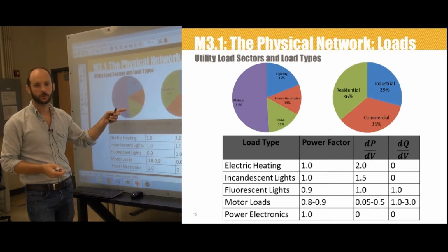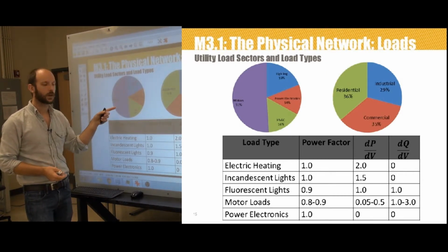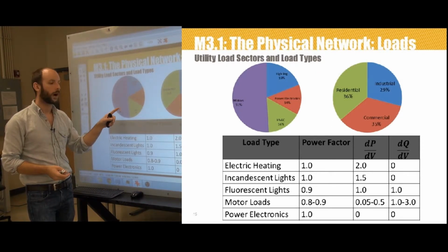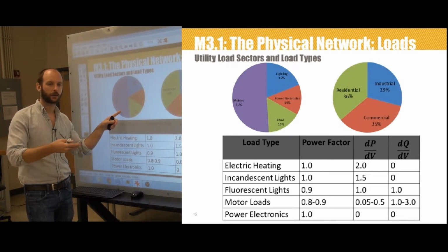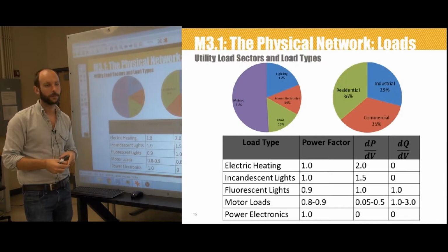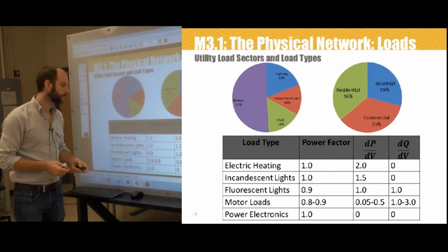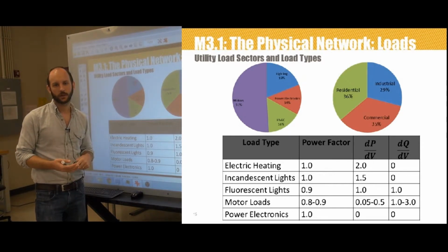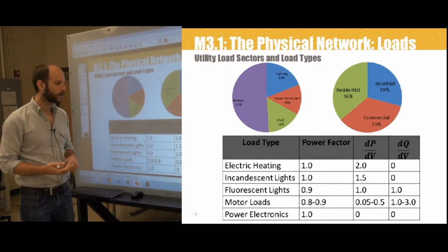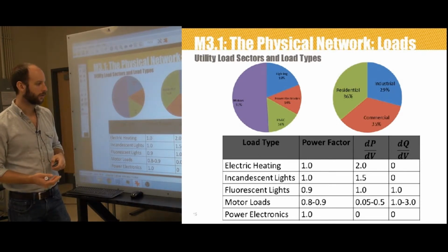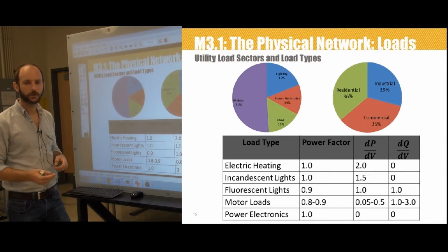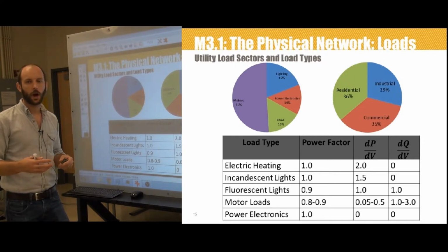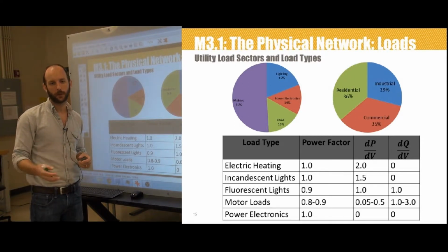Although motor loads do tend to dominate the system, which does explain a little about why we said earlier that the power factor of the grid looks inductive. For each of these load types, the load is going to behave differently in response to changes in the supply voltage, magnitude, and frequency. So what happens to these devices as they're operated with deviations from normal supply?